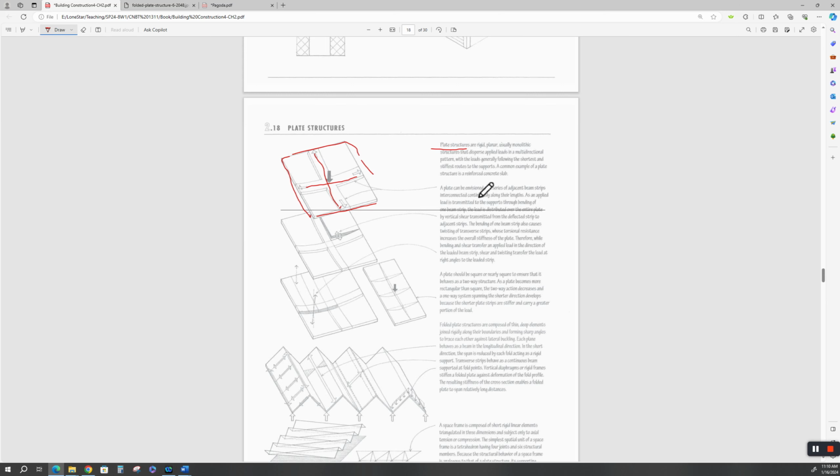You could pretend there are additional beams, vertical shear transmission in the plate, in between these imaginary beams, but you just don't have these beams here. This is the main stress ribbon. The whole slab is reinforced, so it acts as a whole bunch of these stacked together that way, and a whole bunch of them stacked together that way.